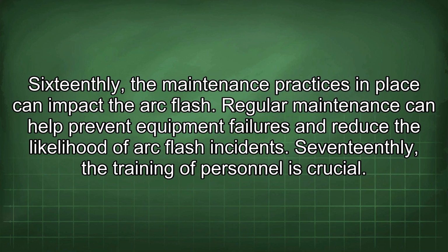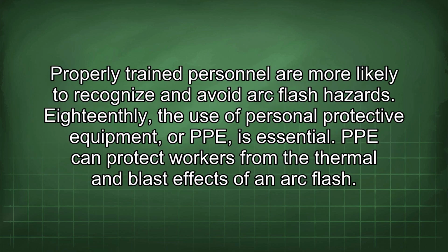17thly, the training of personnel is crucial. Properly trained personnel are more likely to recognize and avoid arc flash hazards. 18thly, the use of personal protective equipment, or PPE, is essential. PPE can protect workers from the thermal and blast effects of an arc flash.